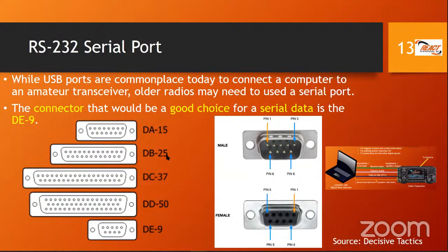Right. So sometimes we may only be familiar with DB25 and we call this one DB9. And DB9 is quite fine to call it, because DB stands for D-subminiature. But the correct name, and for the exam, it's not a typo, it's DE9. It's fine for you to call it DB9, but for your exam, know that the connector we're looking at here, that serial port connector, which is a good choice for serial data, is a DE9. All right, hope I emphasized that enough.